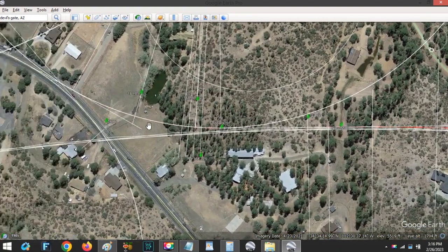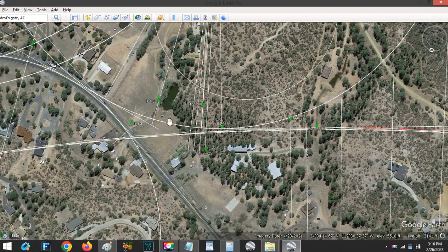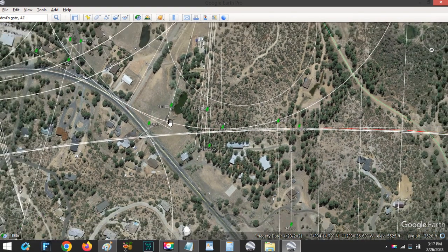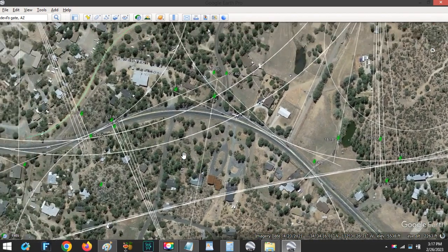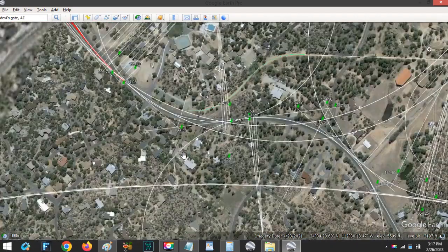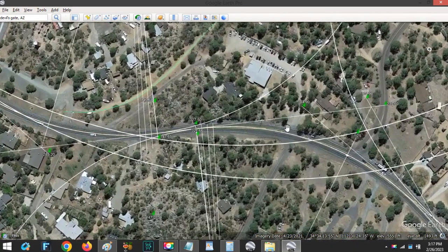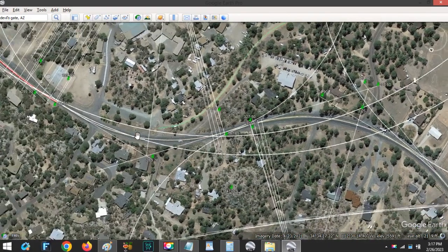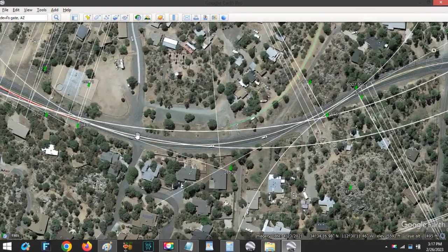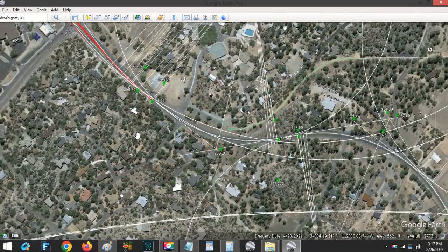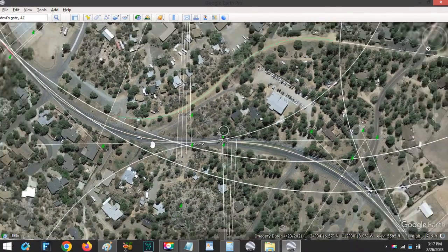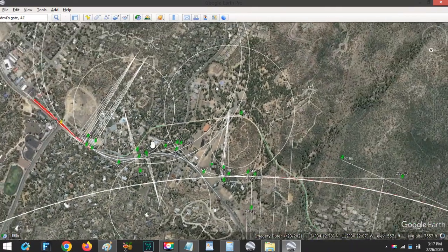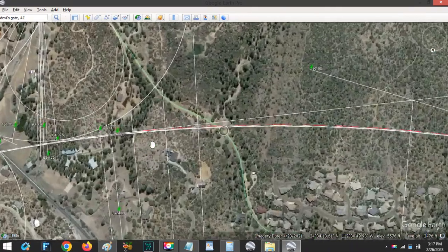That's a curve I created. It's 1,250 feet, so one tenth the size of this 12,500, and then these are curves compliant with the design of the road, which curve is 975 feet, it seems to me, and you have quite a short tangent between the reverse curves, no more than 200 feet, just about 200 feet.